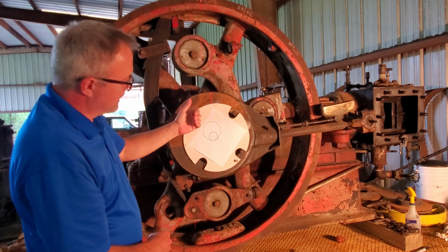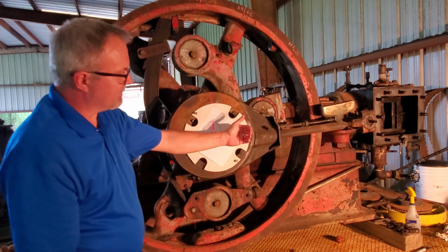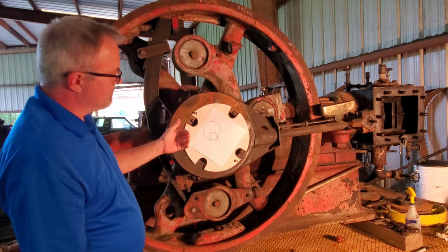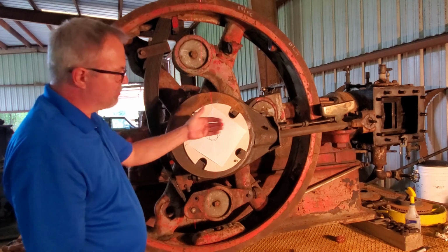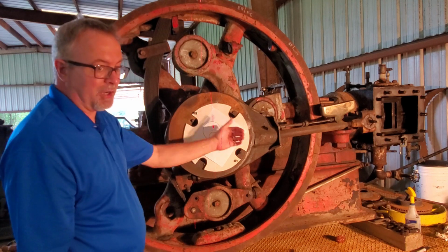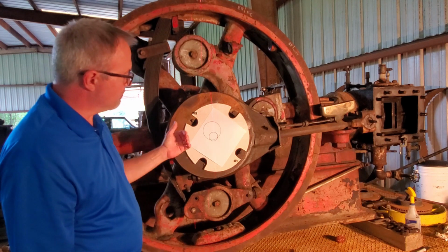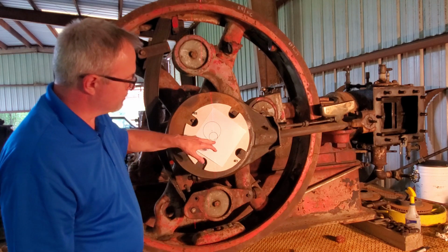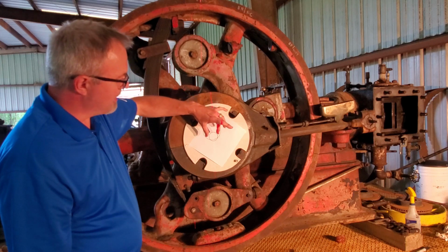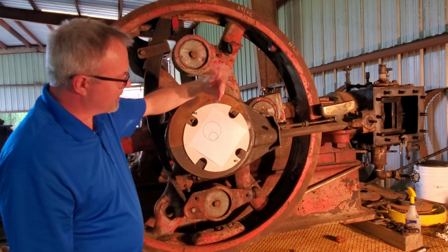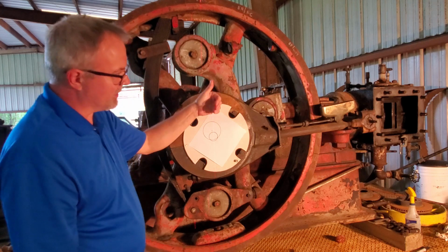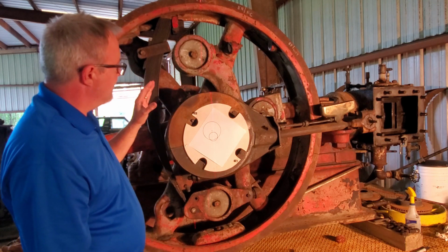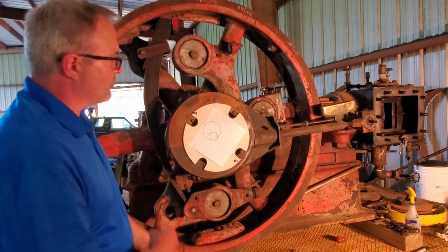reason, because everything that happens on one side of the stroke for the slide valve has to be mirrored on the back side, because both sides of the piston see pressure. It's a double acting engine, so the move has to be symmetrical. The only way to make it symmetrical is to move vertically. That way, the timing events change the same for both the forward and the backstroke of the cylinder. The other reason is because these engines could run in either direction.